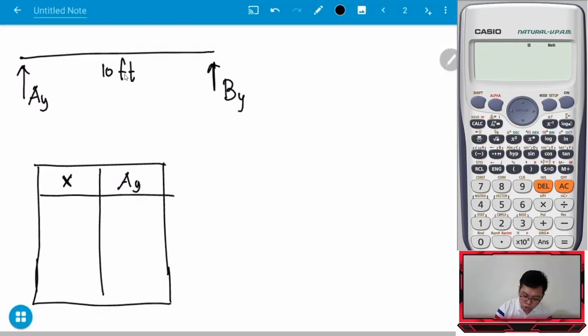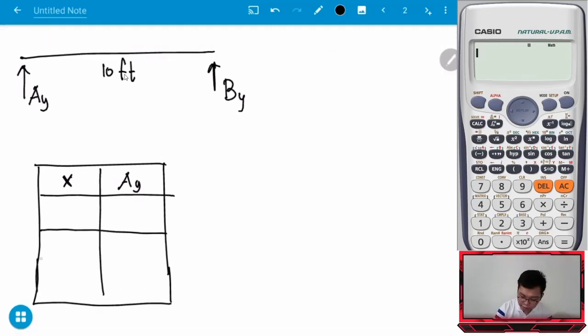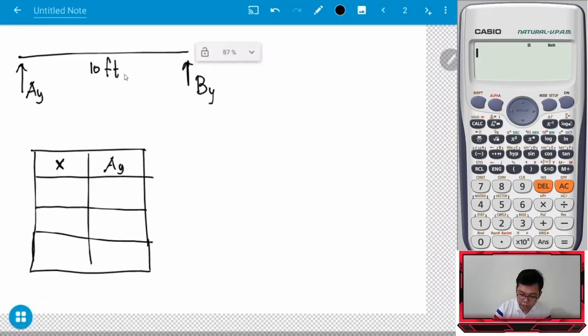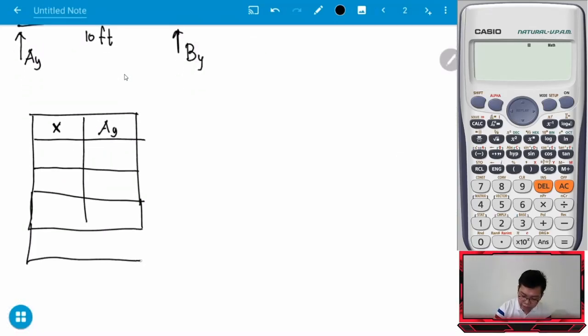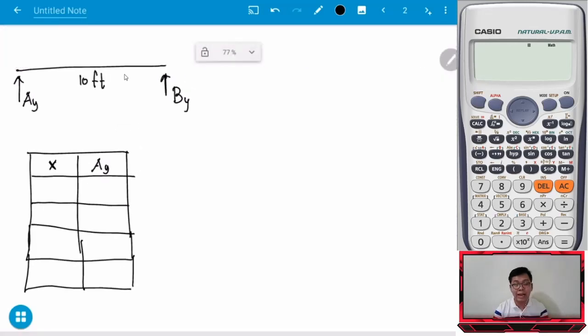Usually, the specific points we use are the quarter points of our beam. The more points you consider, the nicer the influence diagram looks, because you can graph and follow it better. We will use these points to connect the graph, so the more points, the better your lines. Unfortunately, more points also means more cases to solve for shear.